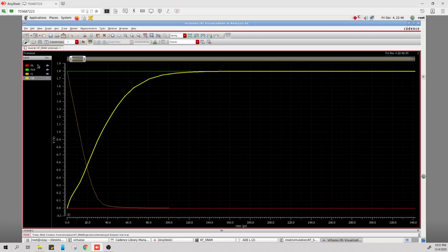Now if you want to calculate the rise time, delay time, whatever you require: from the definition we all know that rise time is the time taken for the pulse to rise from 0 to 90%. Here the 100% value is 1.8. So the 90% value of 1.8 will be 1.62 volts. So we have to calculate the rise time. Around 1.62 will come here, so we will consider the 1.62 value and then the relative time value.